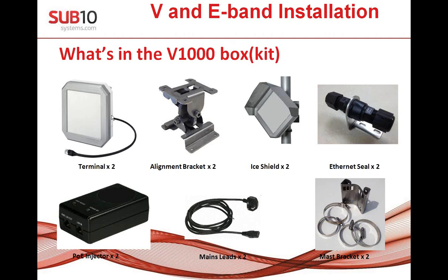What is important, and really keep in mind, the terminal currently comes with a cable which is 1 meter long. There is a plan to make it a little bit longer, but very important, on the back part of the terminal, you will see later in the picture, there is a connection going to the unit, and this connection is tested by Sub10 to be waterproof. And now you can also see there is tape protection, and if this tape is broken, you are losing the warranty. Keep in mind, this is really checked to be sure that there is no way water can get in, and all customer connection is done on this port using the seal kit.